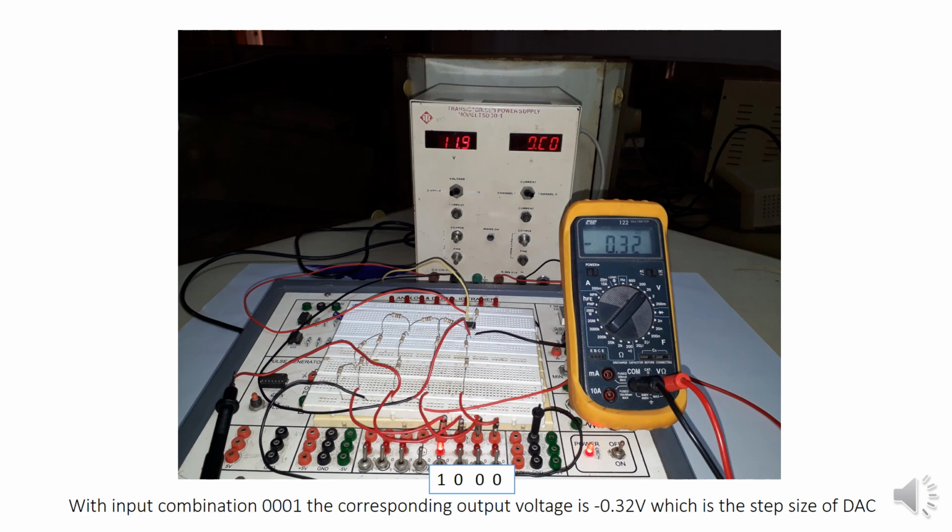If you want to reduce it further, you can reduce the RF value. Resistor values will not affect the outcome of this digital to analog converter. Only the feedback resistor, the value of RF, will determine the step size of our DAC.